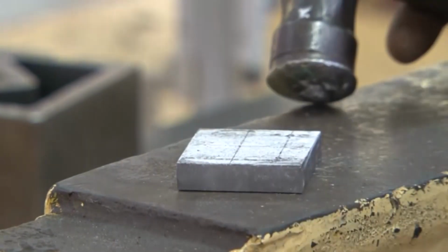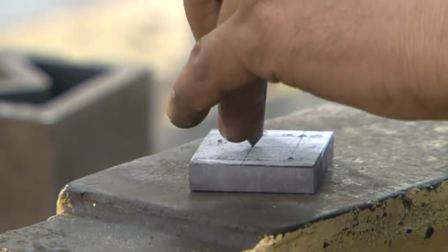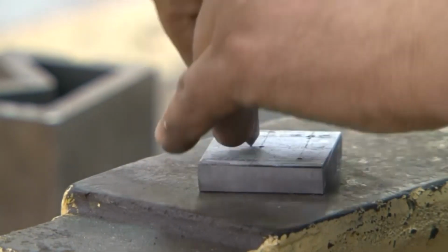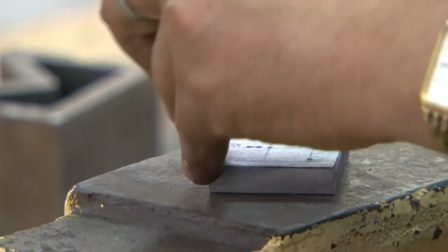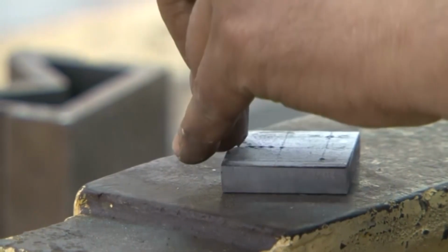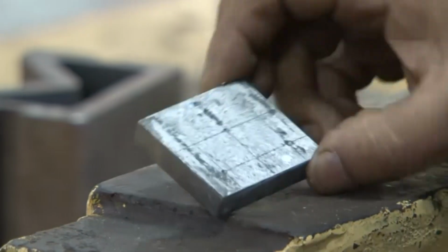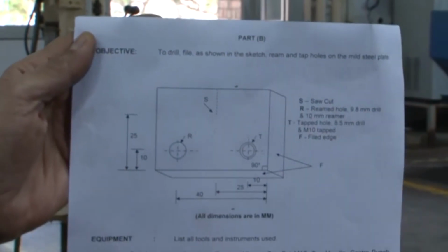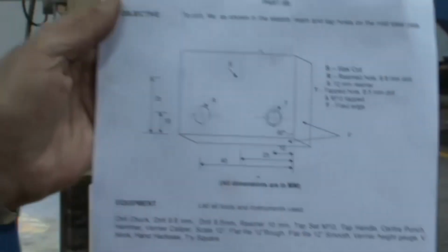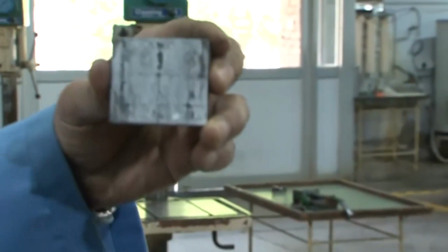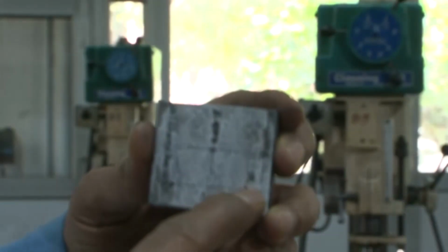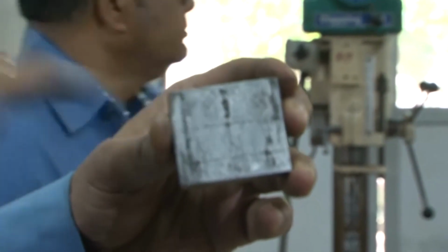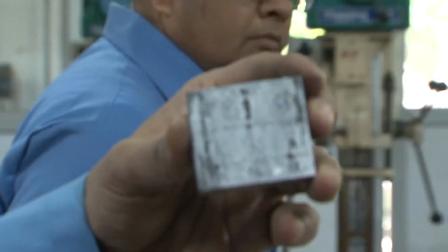So, these are the two holes. These are the centers of the hole, where you have to drill the hole, and also there is a slot to be cut. So, for slot cutting he is also taking the marking. The slot you can see here from the drawing. This is the slot that we will be cutting, because there is a sawing operation, and that operation also we will demonstrate to you. So, these are the markings, and the centers are marked as well as the position for the slot is also marked with the help of the hand punch.